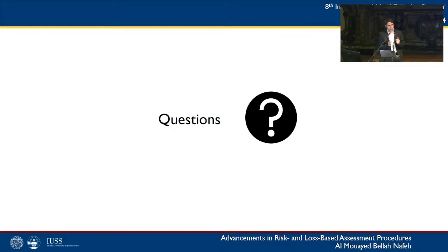To correct a misconception, we did not actually do... are you talking about the cloud analysis of the proposed methodology, of the tool, right? Yeah. Okay. So this cloud analysis takes into account 500 ground motion records that were selected for a suitable range of magnitude and distance ranges, and taking into account multiple intensity measure levels along the way so that we are able to characterize the structural response from early on from the elastic range all the way to structural single degree of freedom systems. Okay. And the database, of course, is available in the GitHub.